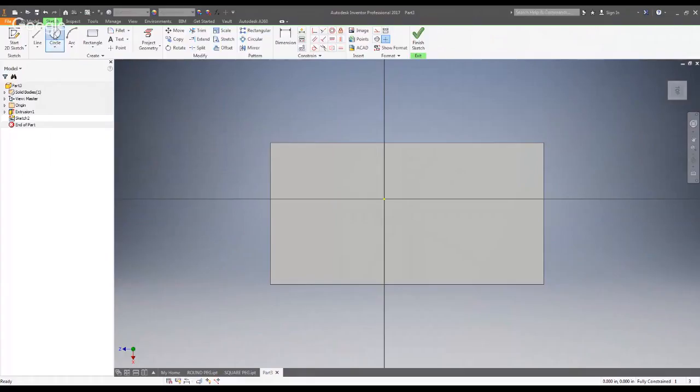So I'm going to do this hole by drawing a circle on the board and then dimensioning that circle to be 1 inch in diameter. And then I'm going to position the circle on the board. And when I position it, I kind of want it to be equally spaced here. It doesn't tell you exactly these holes necessarily, but I'm going to do my best to get it equally spaced.